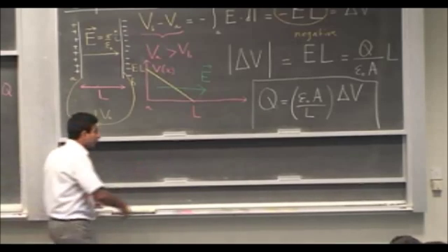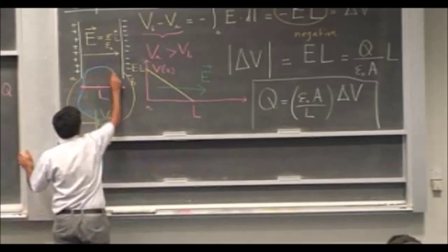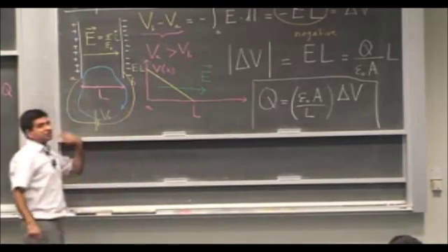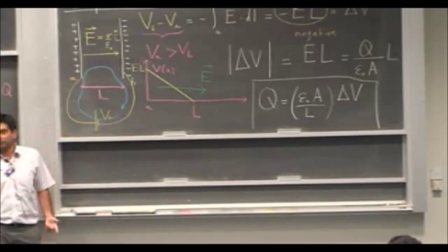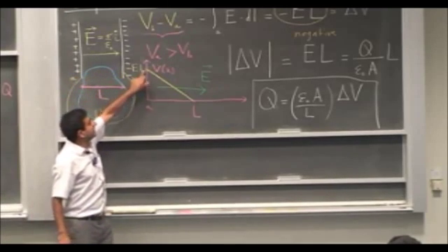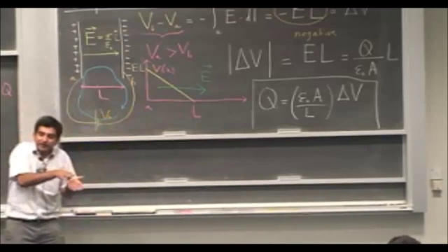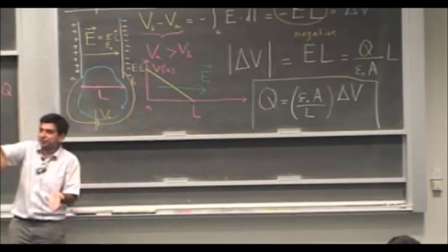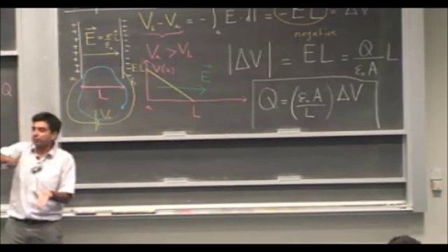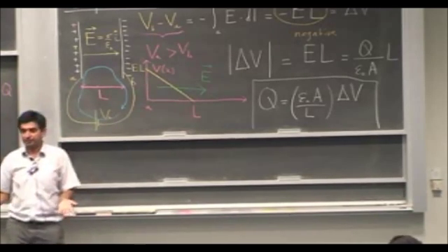Okay? So if you go around this path, this is a closed path in space. The total change in potential should be 0. So here you're going from a positive to negative potential, from EL to 0. And here inside the battery, you are going uphill, from a lower potential to a higher potential. So the potential difference in the complete round trip in this circuit is still 0.